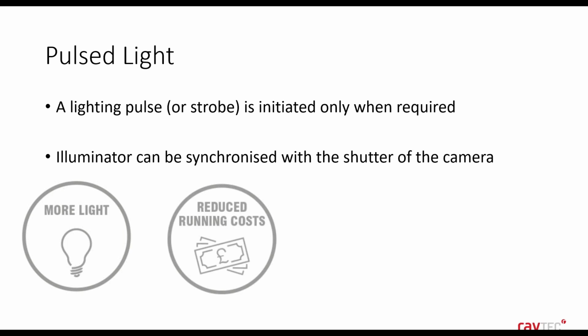And because when we're pulsing the light, the LED illuminator is only on for short bursts of time, it's actually switched off for much longer periods than it is on. So this can help to significantly reduce overall power consumption too. If power saving is the primary focus of the setup, and for some applications it may be one of the primary focuses, you could actually reduce consumption by as much as 95% if LEDs are pulsed without overdriving, so running at the same power.